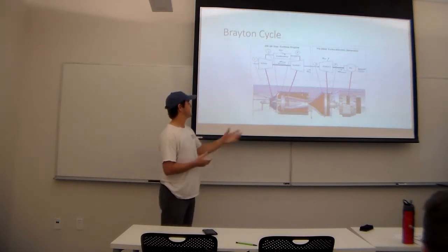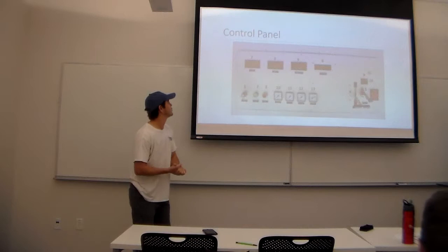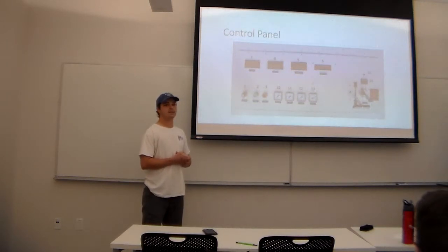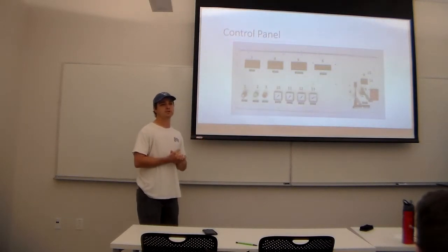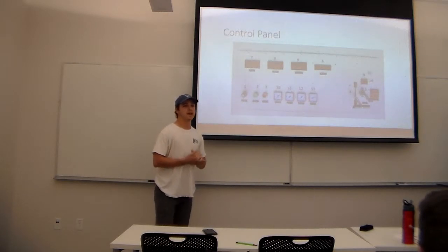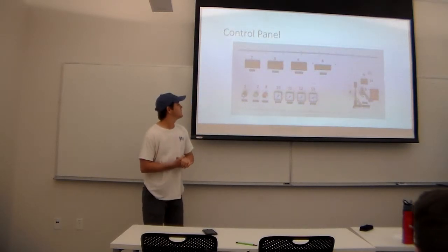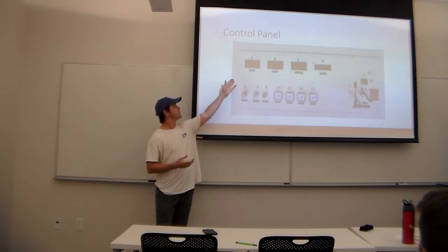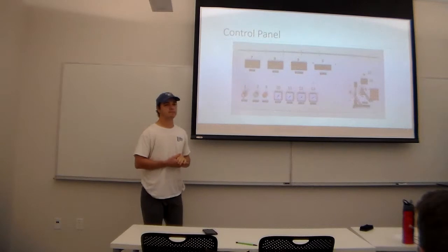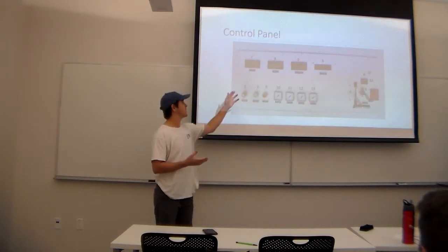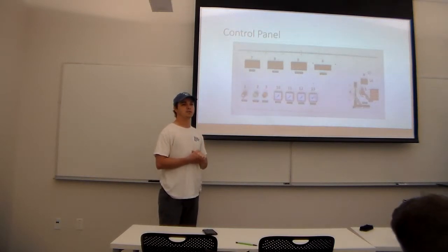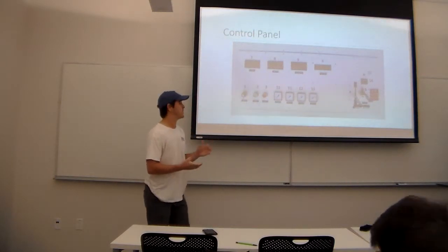the experimental apparatus. So this is our control panel. We have an on-off switch right here. We have a couple of pressure gauges that monitor the fuel pressure, the oil pressure, and the air pressure in the inlet, and then we also have a turbine inlet temperature monitor, and RPM for the first turbine and for the second turbine. 8, 9, and 6 will shut off if your parameters get out of control, and it will tell you when.